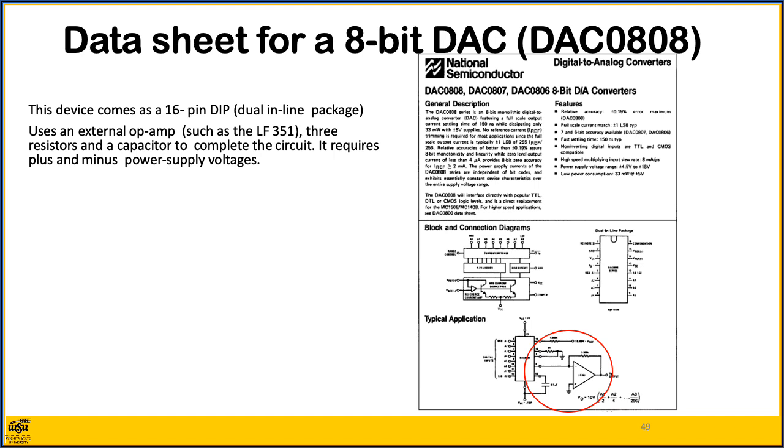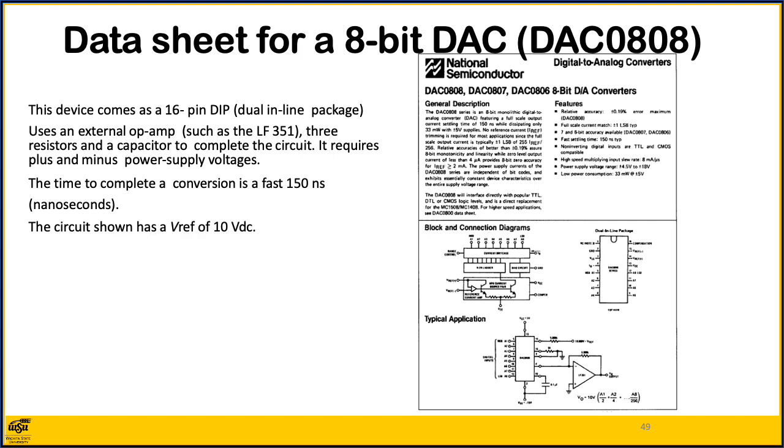It requires plus and minus power supply voltages, in this case plus and minus 5 volts. The time to complete a conversion is a fast 150 nanoseconds, and the circuit shown has a reference voltage, Vref, of 10 volts DC.